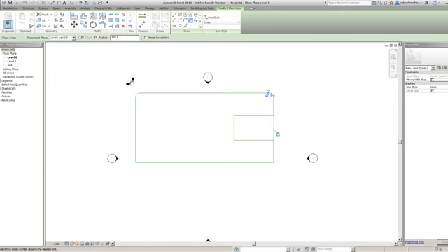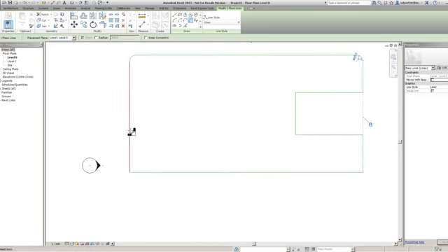Nice and simple. Now what I'm going to do, I'm going to untick the radius tool. Okay, and then I'm going to pick this line and then this line. I'm just going to move my mouse. And you can see basically I'm manually putting in the radius that I can do. Okay, if I move my mouse outside of the area that you can actually use to put the radius in, it comes up with a little stop sign. And likewise, if I go too far, so that it's actually too far to fit the radius in along that geometry, the same will happen. So I'm simply plonking in the line where I want the radius to go.